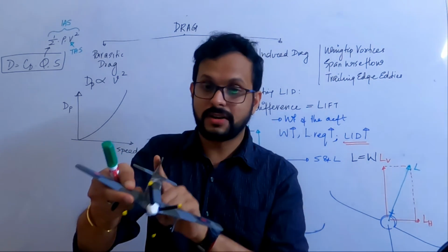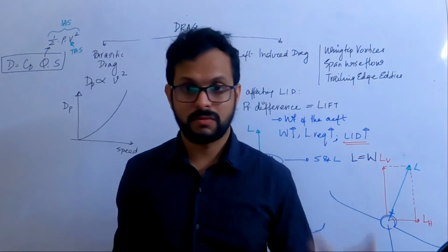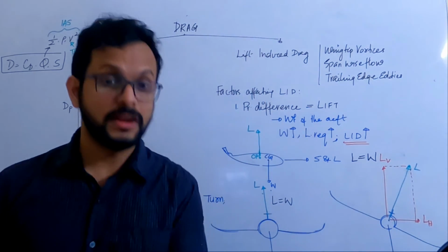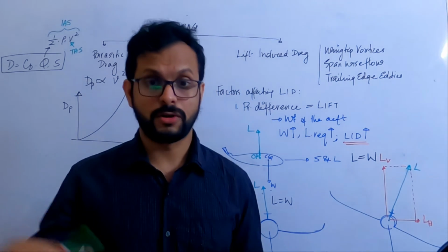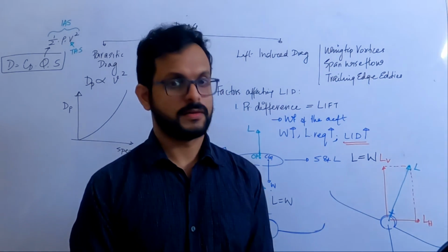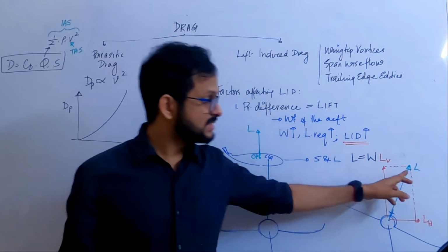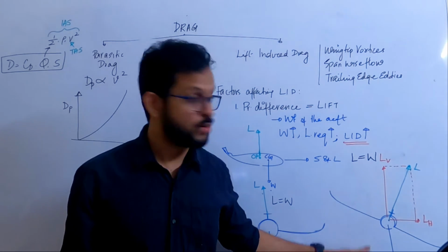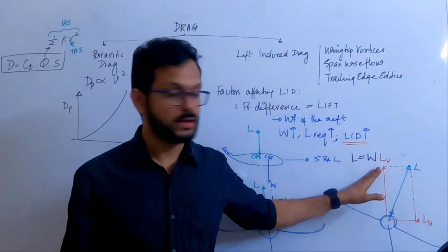Now you have the rudders in place, which help you balance this. And if you don't do it, remember in your navigation instruments, we have studied about slip and skid, based on whether you give more rudder or less rudder compared to your turn. Right? So basically, our idea here is to understand that this entire lift is no more countering the weight. What is countering the weight here? Only the vertical component of lift is going to counter the weight.